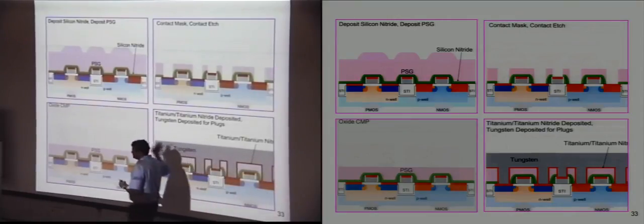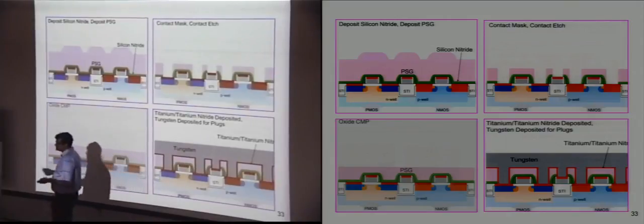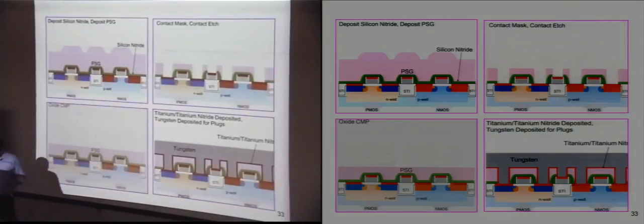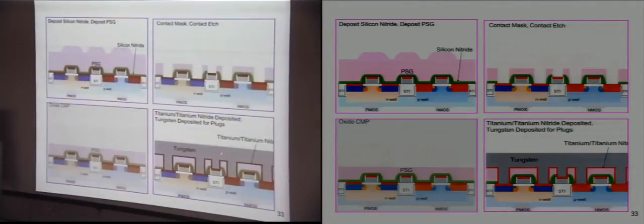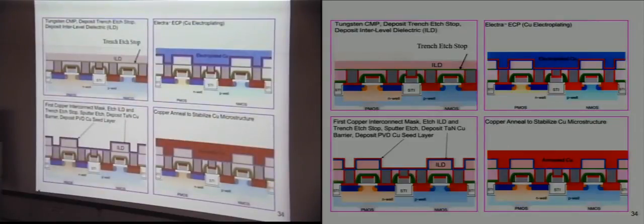So you have put the first metal line down with tungsten, and then of course after you have deposited tungsten everywhere, you are going to CMP the tungsten away such that the tungsten is only at these locations. Okay. So look at the color, the dark brown, dark gray color tungsten, which was everywhere, has been CMP'd away. So we only have it at these few locations.